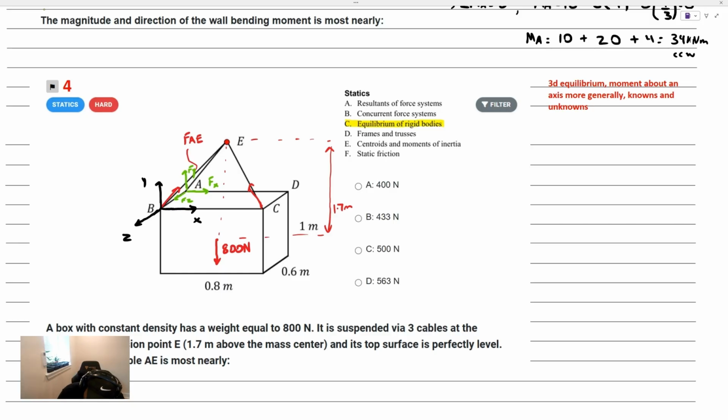The force in the x direction is parallel to the x-axis. It can't produce rotation around the x-axis either. Only that force Fy will be producing a moment or rotation around the x-axis. You can see that those other two forces are intersecting the x-axis, so they won't produce any moment. But that 800 newton, it's going to produce a moment, right?